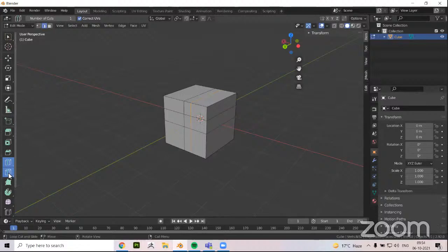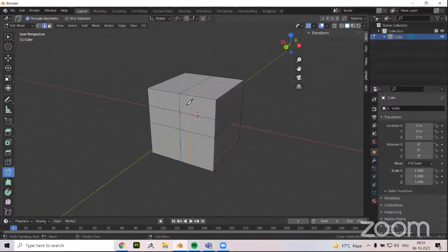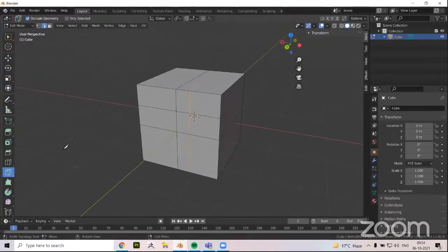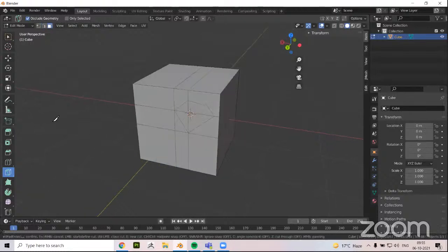And the next tool is the knife tool. With loop cut, a whole loop was automatically created at the center, but suppose we want to manually input points from the 3D viewport, then we can select the knife tool and start cutting things. Wherever I click my mouse, it'll create an edge there and also a vertex, to create whatever shape we want. Once I have my cut finalized with whatever shape I have, I just need to press enter and we have this shape made here.